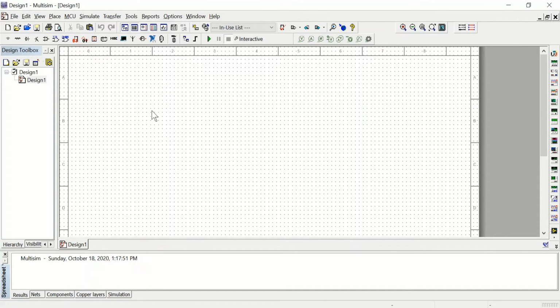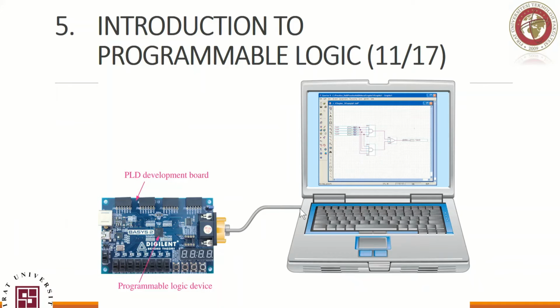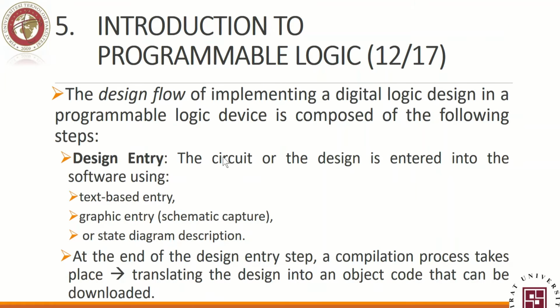You can create the circuit first, then convert it to a bit stream or simulate it, and then you have the functionality of a tool that allows you to connect the device you need to program to a circuit, like a programming board. So we create it in software, we simulate it, then we need to install it to the programmable logic device.